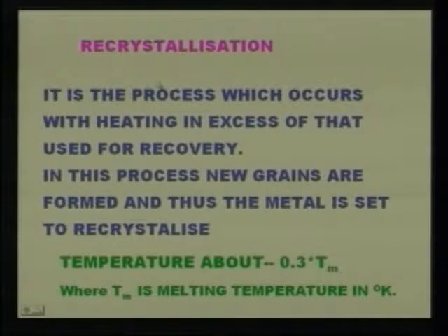Now, let us know about recrystallization. Recrystallization is the process which occurs with heating in excess of that used for recovery. In this process, new grains are formed and thus the metal is said to recrystallize.